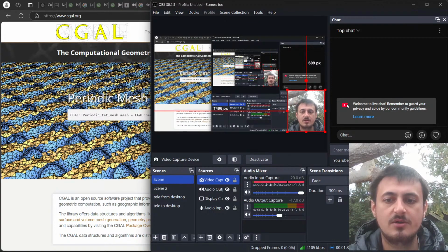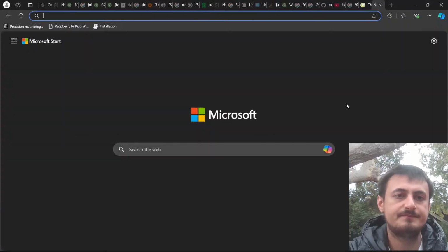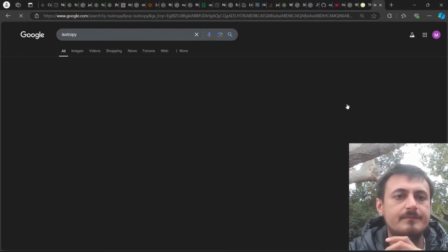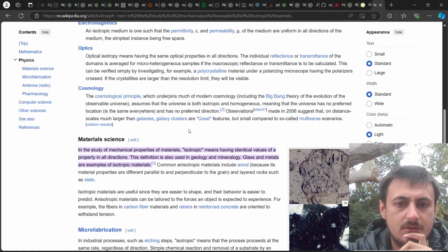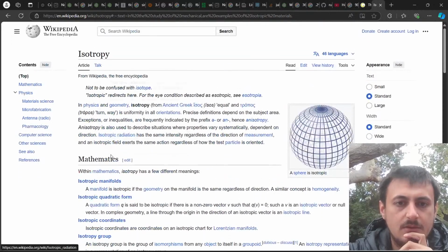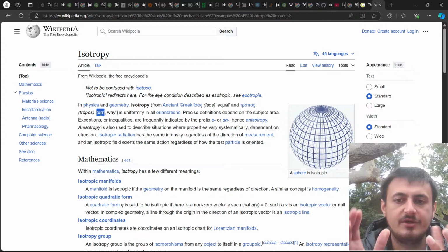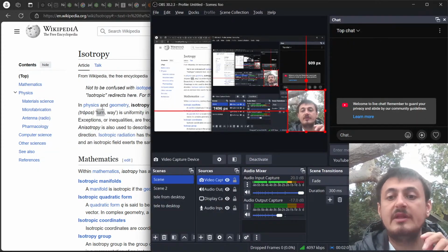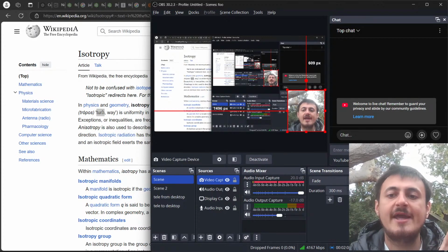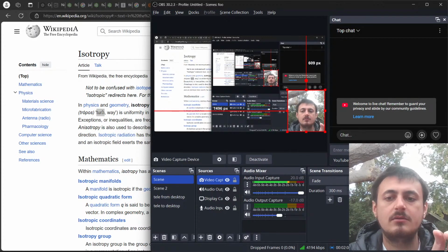So it's much stronger in one direction than the other. And there's a name for that, which is called isotropy, which basically means the same, equal in every orientation. So, anyways, the name for 3D printed parts is that they're anisotropic. They're not the same in every direction.